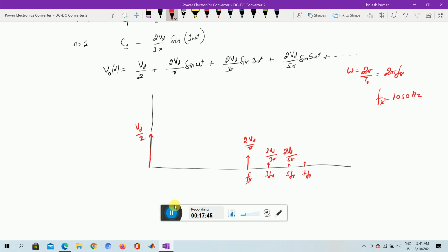And this is what we understood, that if we have this output voltage as a DC of duty cycle half, that D is 0.5, and V0 is changing from 0 to Vd and 0, like that, we are getting a DC value. This is the VDC we are getting.